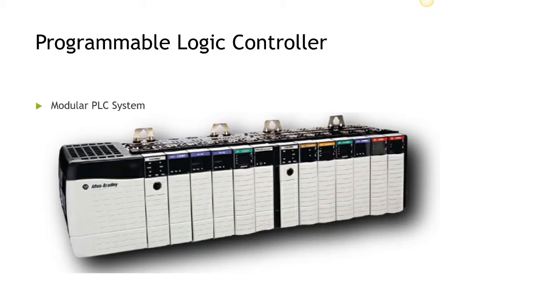So if we wanted to duplicate the same functionality that we had on that previous slide in our integrated PLC, we'd have to at least buy the chassis, which has the power supply in it. We would have to purchase a central processing unit card. We would have to purchase an input card and at least one output card to be able to come up with the same configurations that we could do in that compact or integrated PLC. And the cost is significantly higher in this modular offering.